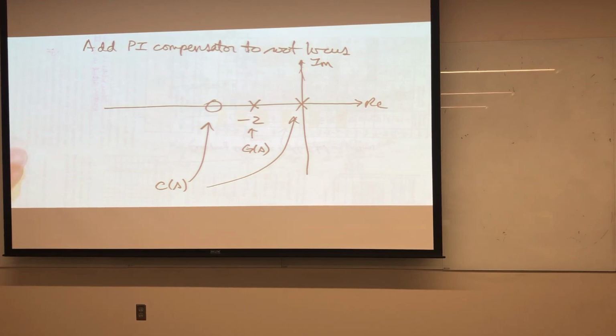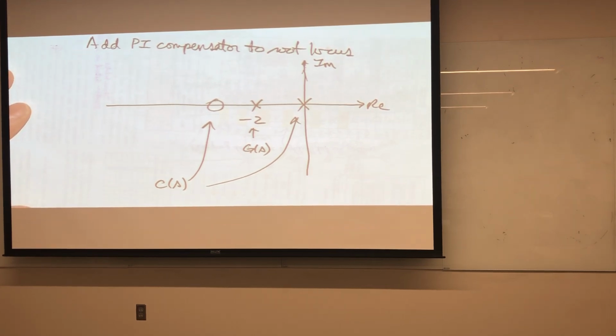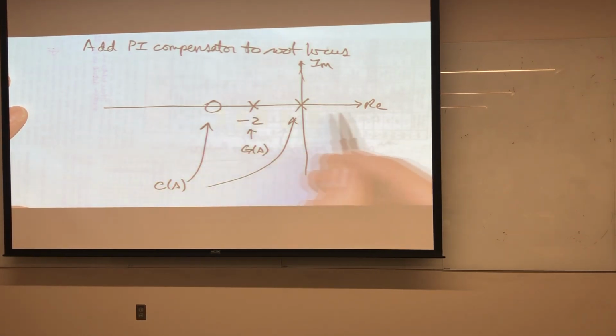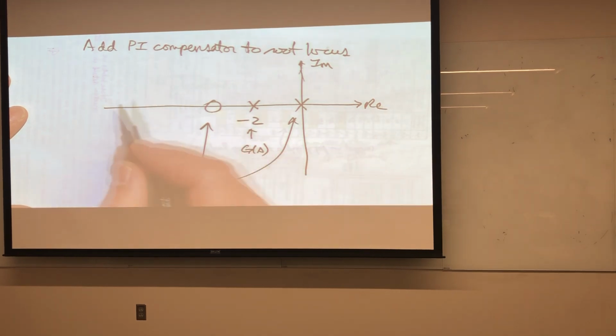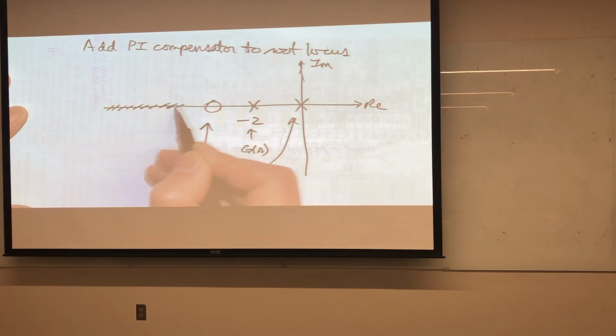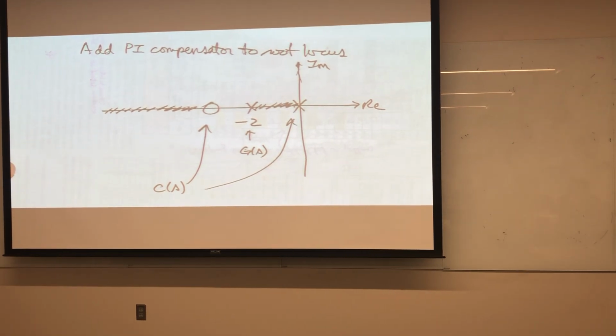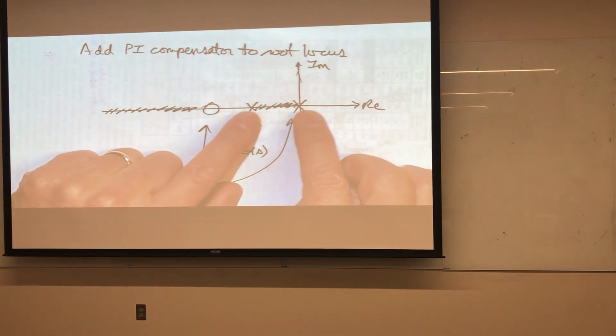Okay, now let's take a look at the root locus diagram. One of the rules is let's take care of the real axis. See where on the real axis there could be closed loop poles. And we'll see that there could be some here and could be some here. We have two branches because we have two poles.